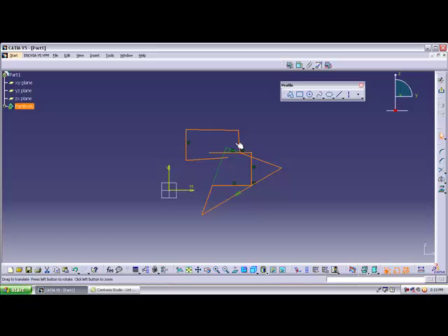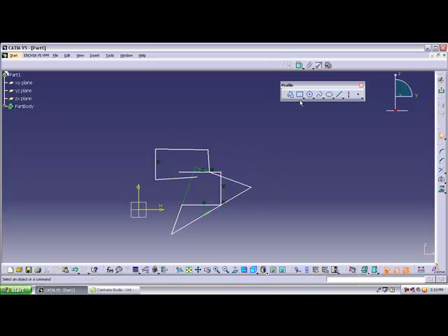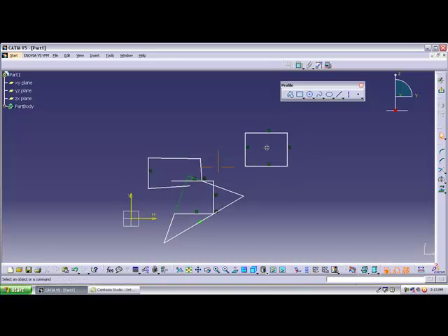And next thing, suppose right now I show the example of a rectangle. While drawing the rectangle, you will get an exact rectangle with horizontal and vertical constraints. But previously it didn't get the horizontal and vertical. Why? Because I turned off the geometrical constraints. How did I turn it off? Let me show.